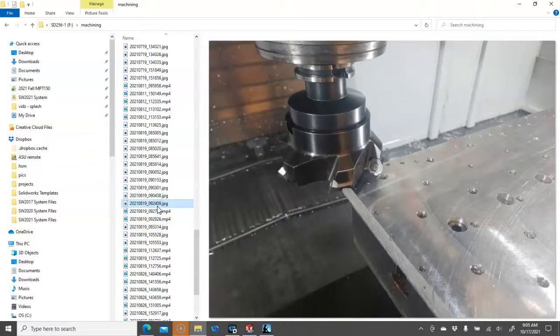So to make sure that this is flat, this uses a 5-inch 8-flute facing mill, and this spins at about 800 RPM and moves at about 10 inches a minute. So if we run coolant, it's a lot of splashing, and we'll take probably about 5/1000ths off just to take those previous sacrificial cuts out of the top surface.